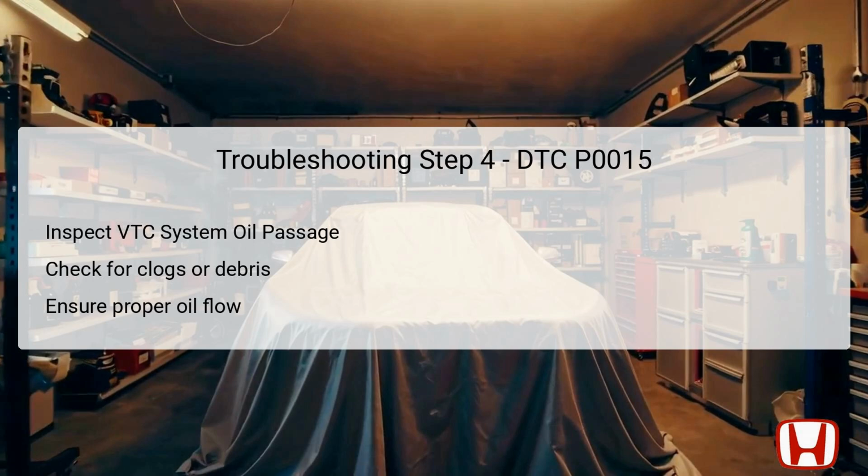If during the inspection, any debris or clogs are found, they need to be removed and any underlying issues addressed to prevent future occurrences. Ensuring the system is free-flowing is vital for maintaining proper variable valve timing and overall engine health.